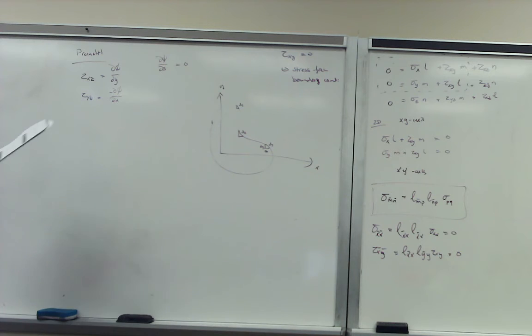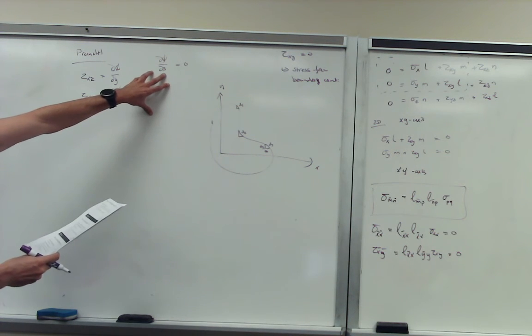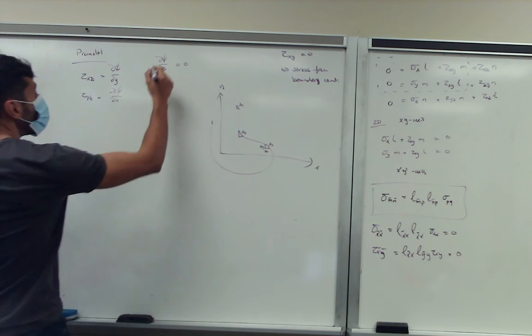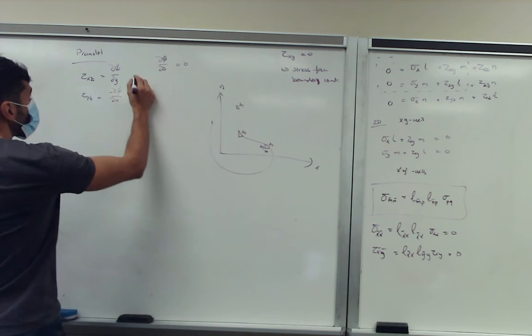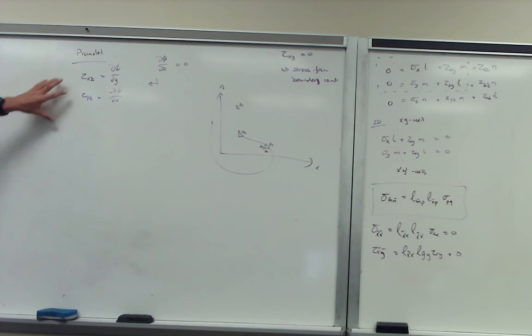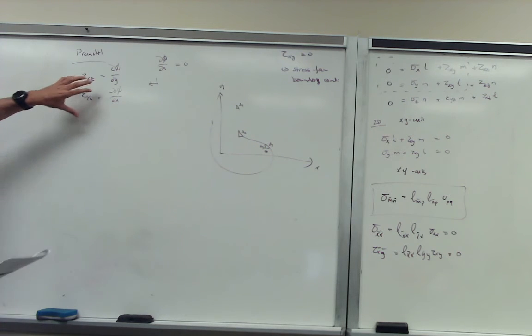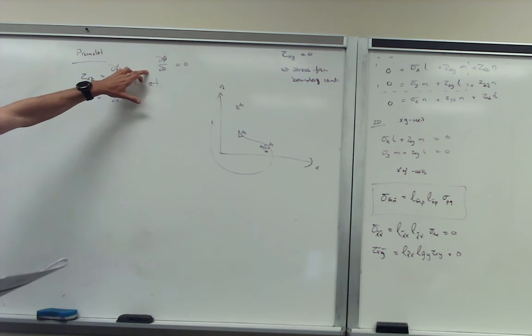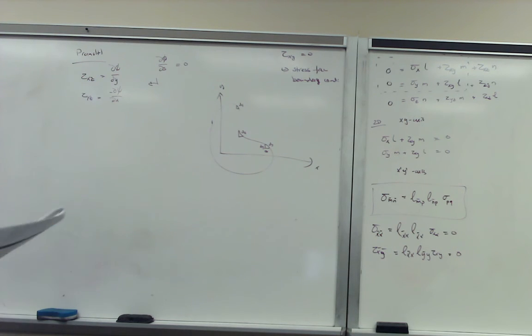Well, the variation with s must be 0. So we can also see that this statement that we got from the boundary conditions does not affect what we earlier assumed our stresses look like, since this is only a function with respect to x and y, while this is a function with respect to the boundary s.